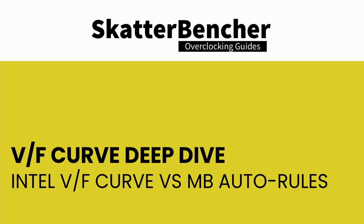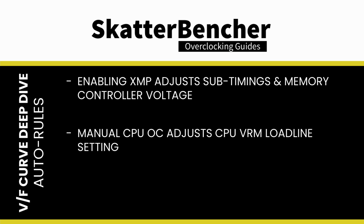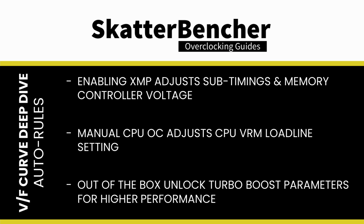The last topic I wanted to cover in this segment is the impact of motherboard auto rules on our voltages. Auto rules are automatic settings that help make the overclocking experience more simple and more straightforward. Typically, auto rules consist of pre-programmed settings that change depending on the changes that the user makes in the BIOS. Examples include, when enabling XMP, the motherboard may adjust memory subtimings and memory controller voltages to ensure stability. When manual CPU overclocking, the motherboard may change the CPU VRM load line settings. Motherboards may unlock turbo boost parameters out of the box to provide the user with higher performance.